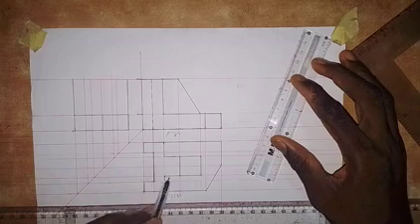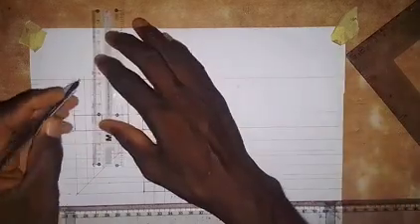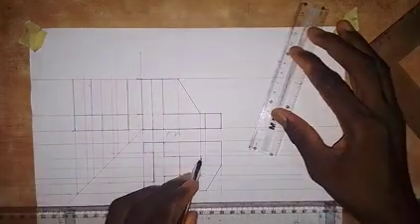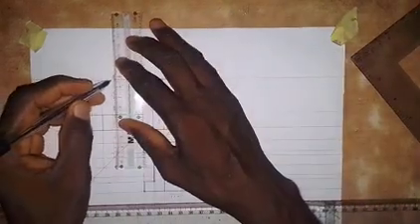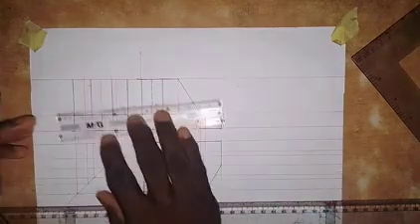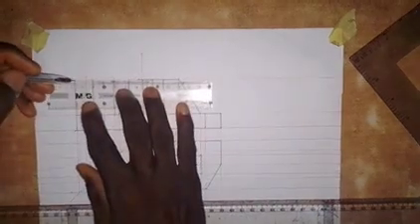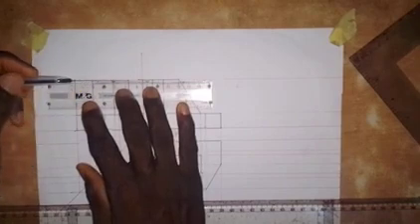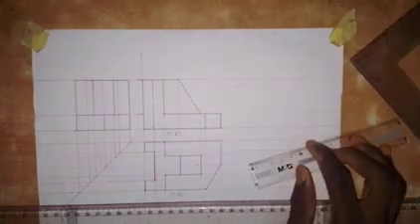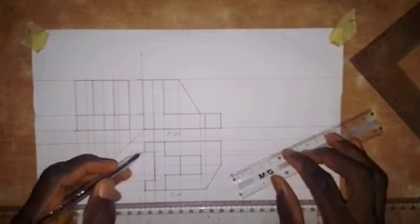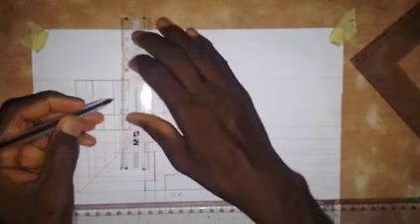Then what about this rectangle that we have here? Let's follow this line like this. So we have the rectangle, so draw this line as a vertical line, and at this point here, draw this line as a vertical line. Okay, so this line will be a thick line all through. So we're almost done with the right side view. What we have left is the line that will be hidden at this point.